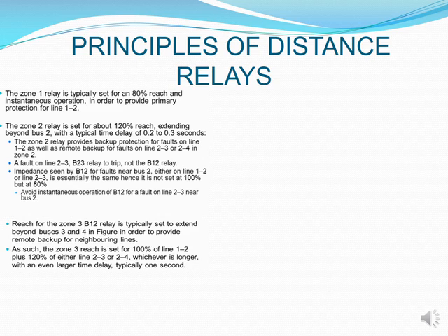Okay, so for your zone 3, how we've defined it in our earlier course where I do protection 3 with the diploma guys, I've standardized that your zone 3 is now 150% reach. But as you can see in the network that we just had now, it's a complicated network. It's not straight lines from point A up until point E.